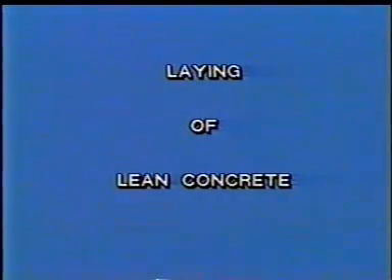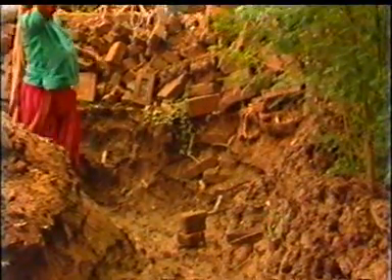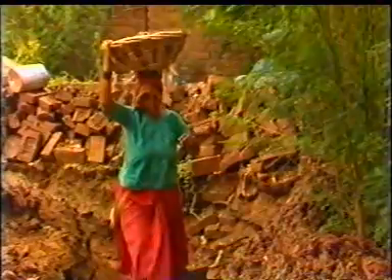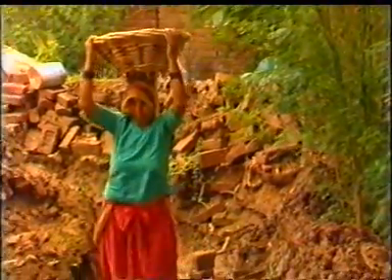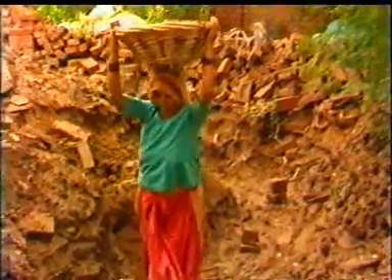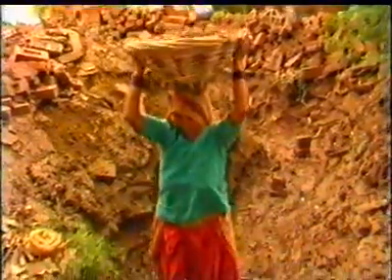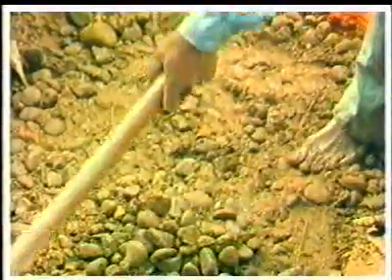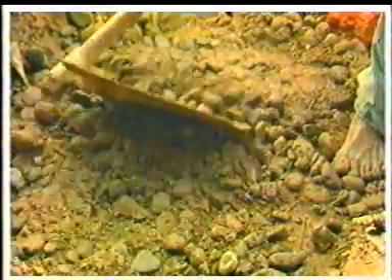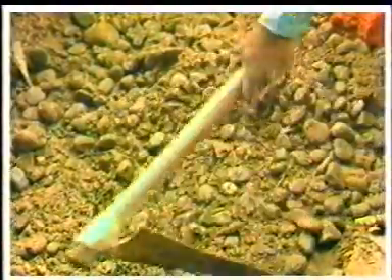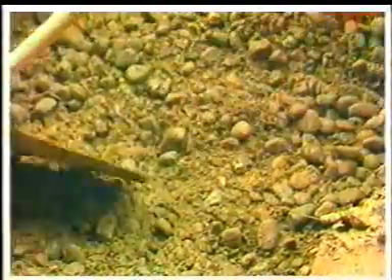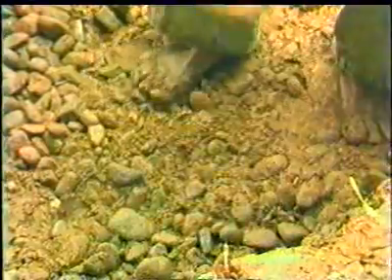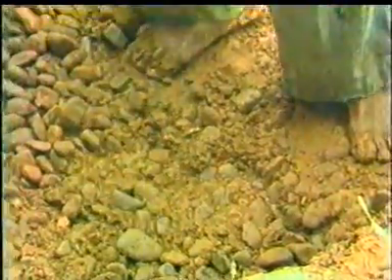Laying of lean concrete. Depending upon nature and intensity of loading, a lean concrete layer of required thickness and proportions is laid in foundation trenches. The lean concrete mix is placed and compacted for obtaining a level surface for foundation masonry.